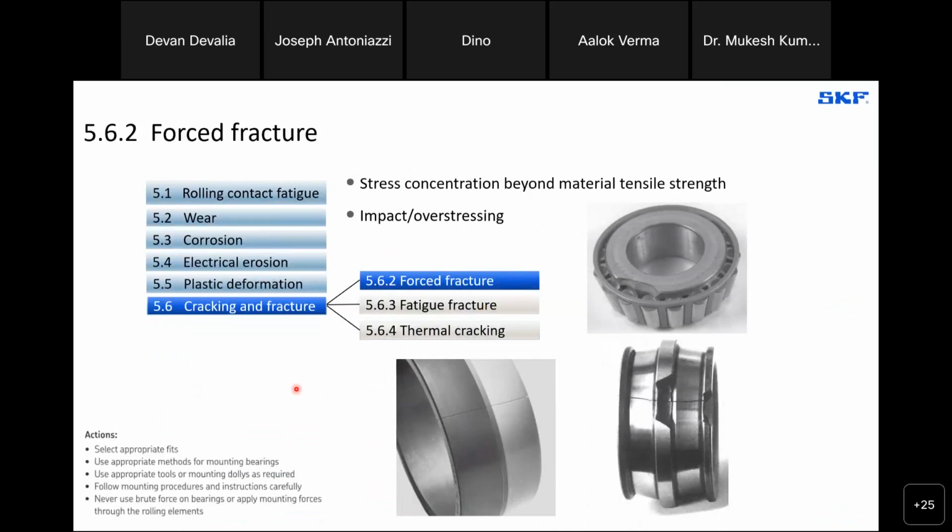Rough treatment can cause fracture. It's a common cause. When bearings are mounted cold and hit with a hammer or a chisel, we might develop fine cracks in the rings of the bearing that eventually lead to separation and through cracks.